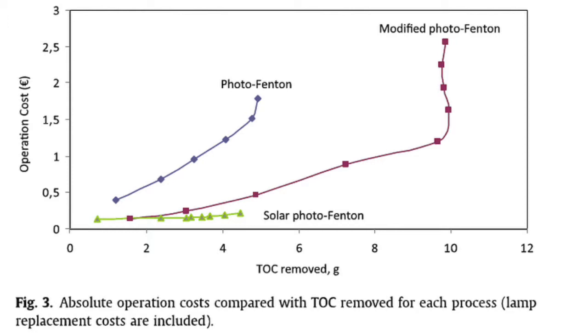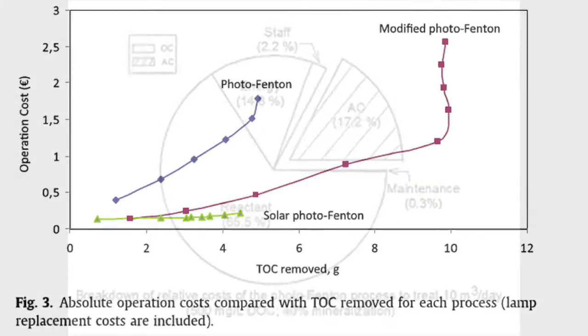Pre-treating wastewater this way enhances the biodegradability of the wastewater, and the residual organic content is necessary for the development of microorganisms. This is why the photo-Fenton process is best when used in combination with biological treatment.